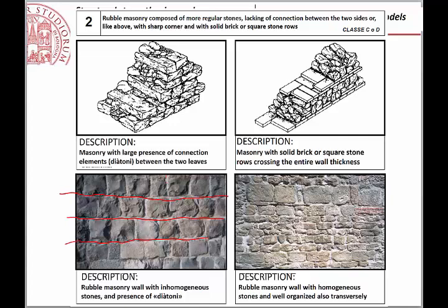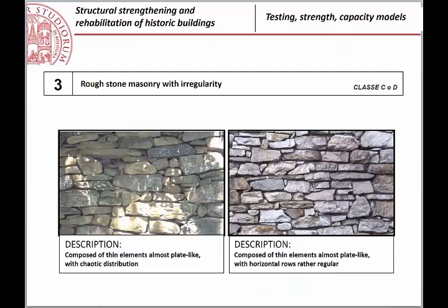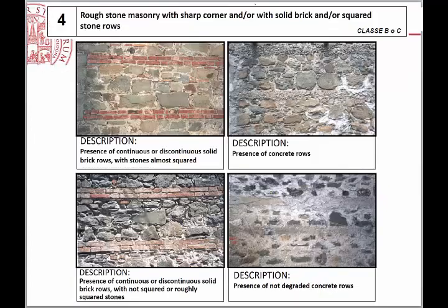But from the point of view of vertical head lines, this is not a good masonry, because the blocks are like a squared shape, and you see that vertically you have almost vertical lines dividing parts of the masonry. So it is better than before, but it's still not a good masonry. Let me go ahead.